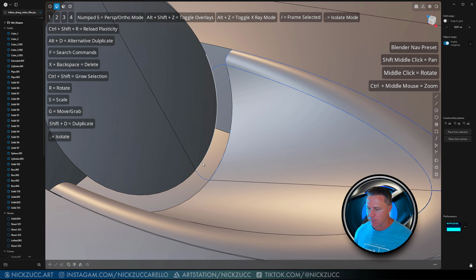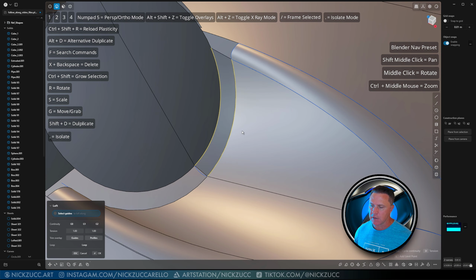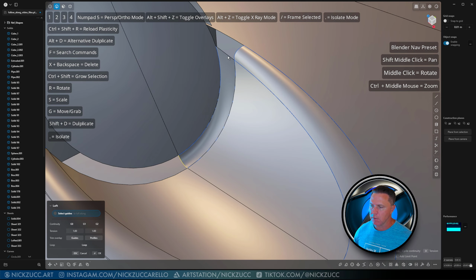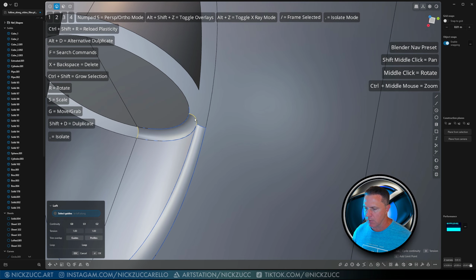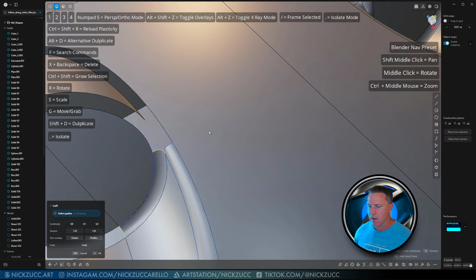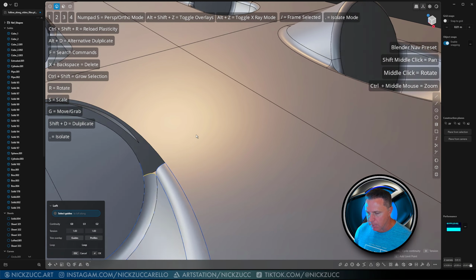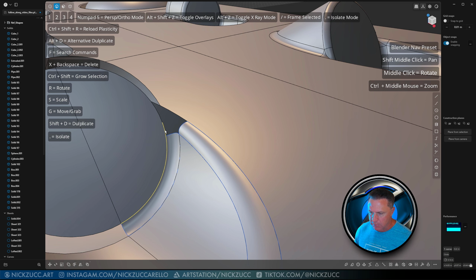So now I've got curve and curve, and we can do a loft. We'll just select those two curves, tap L, hold down Shift. That adds the first rail. And then the second rail will be right here. Hold down Shift, and we can do that right there like that. Okay, I'm actually surprised that this worked here, this curve extended past there.